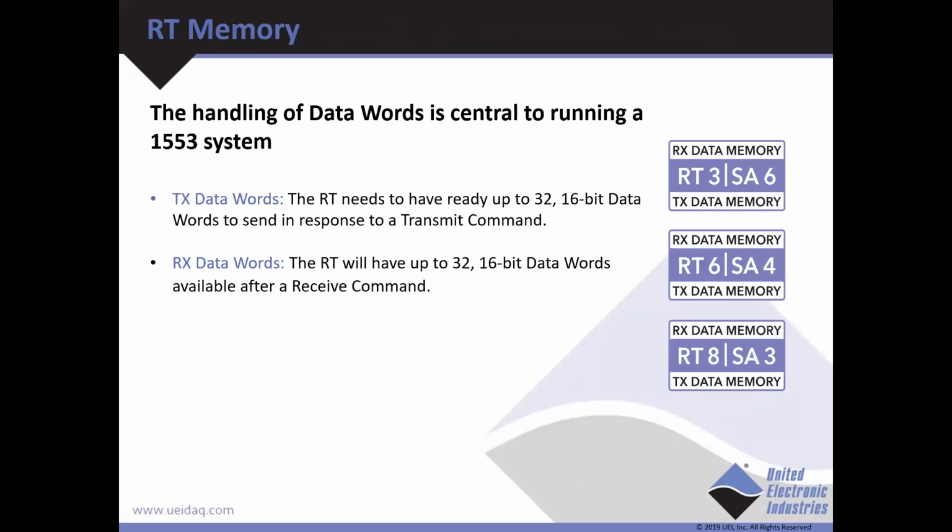The handling of data words is central to running the system. Transmit data words are words sitting in RT memory that will be sent to the BC on an RT to BC command. Receive data words are the words the RT received from the bus controller.